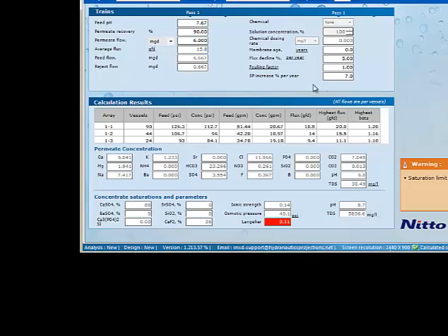And so we have some data now that's here, and so we've got the arrays, the vessels, the feed PSIs. You'll notice it goes high pressure down to lower pressure, concentration, feed in gallons per minute that's coming into the plant, the flux, so gallons per foot square per day, highest flux and the highest beta values that are there. And here's the permeate concentrations. This is what we want. This is the concentrations of our anions, cations that are leaving the water filtration system. And we can also look at these other parameters.